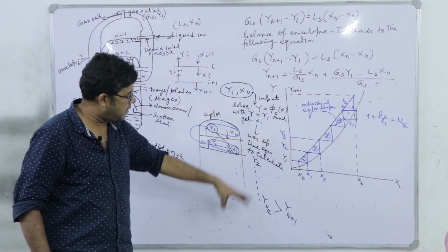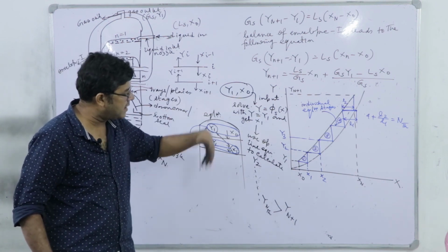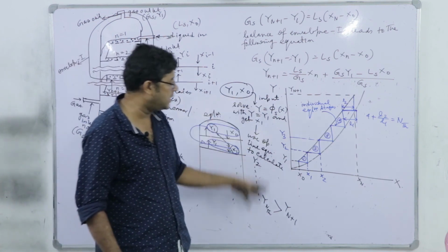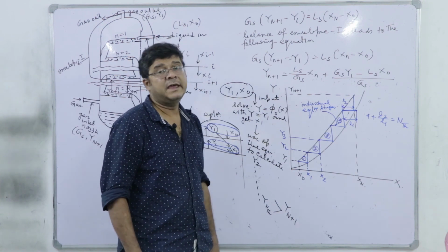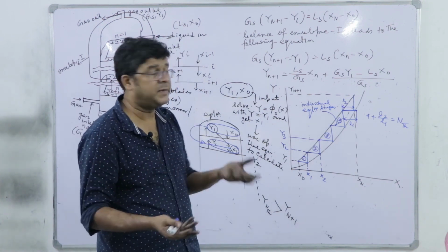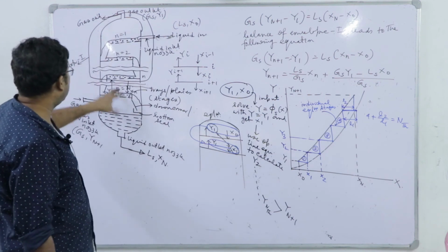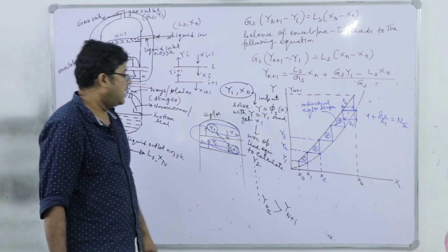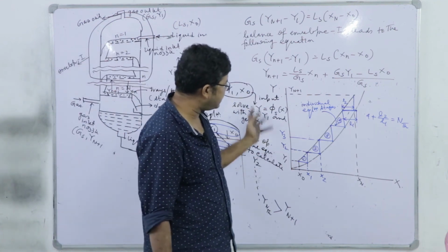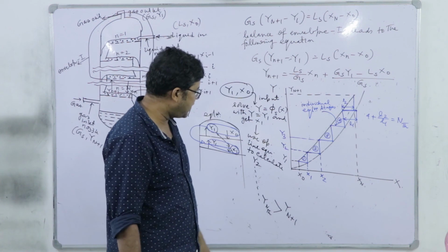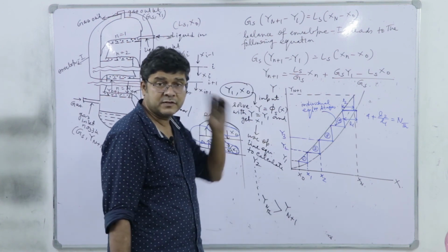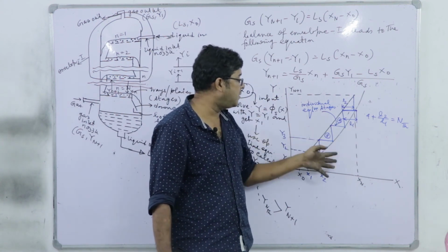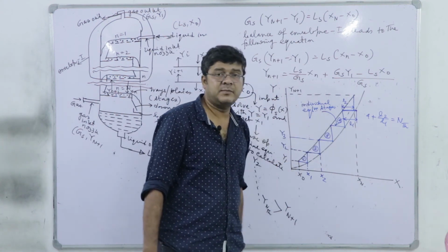This technique of analytical calculation, we will see its modified version in distillation, is called the Lewis-Sorel algorithm, or Lewis-Sorel technique of finding the number of stages in a distillation column. Distillation is much more complicated than this typical plate column, because there we have the feed from some intermediate point, and that has been simplified. This analytical approach is called the Lewis-Sorel technique, and that has been extremely simplified by the staircase construction of McCabe and Thiele.